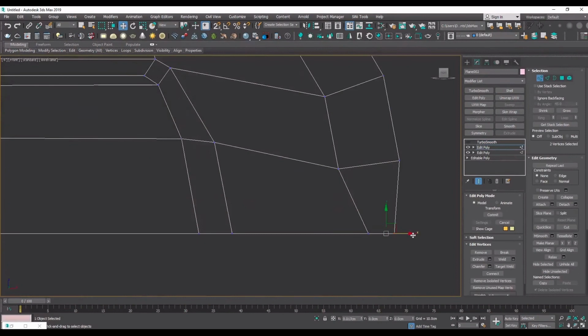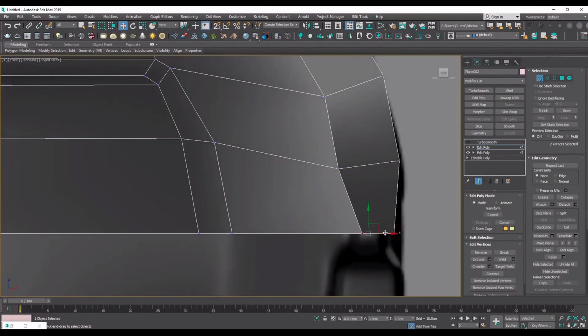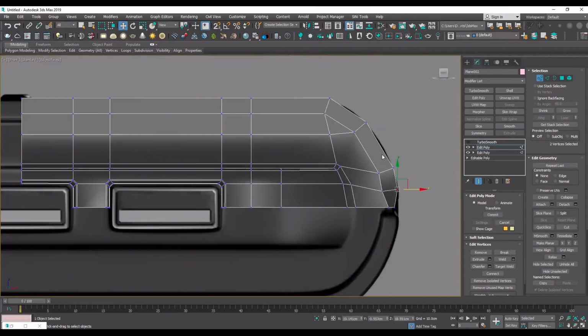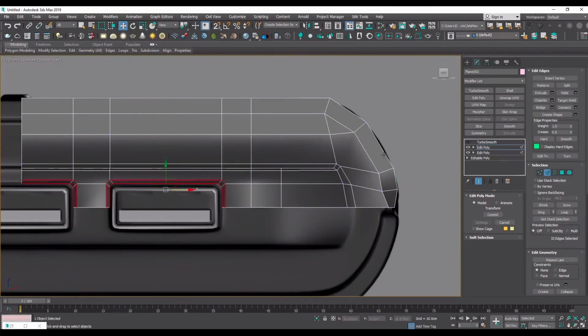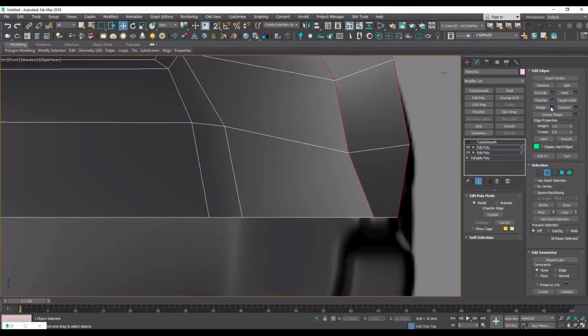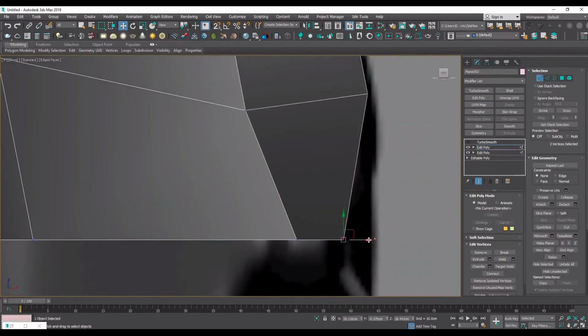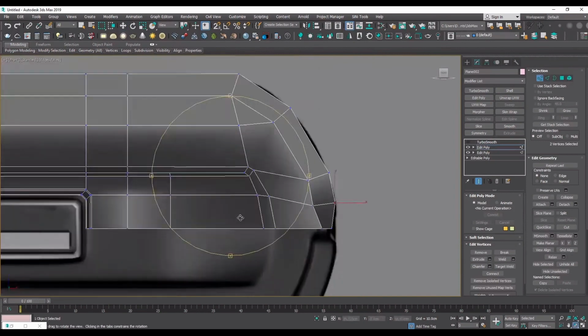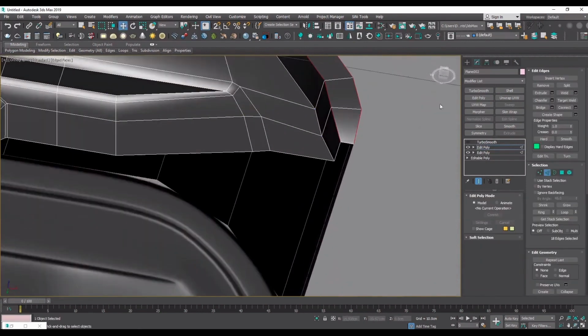Off to the upper part of the model, I'll do some adjustments here because I'm going to also use chamfer modifier on this part, and I select these two edges and I will want to apply chamfer, but now let me just apply some adjustments even further because I don't want the chamfers to basically go inside each other.